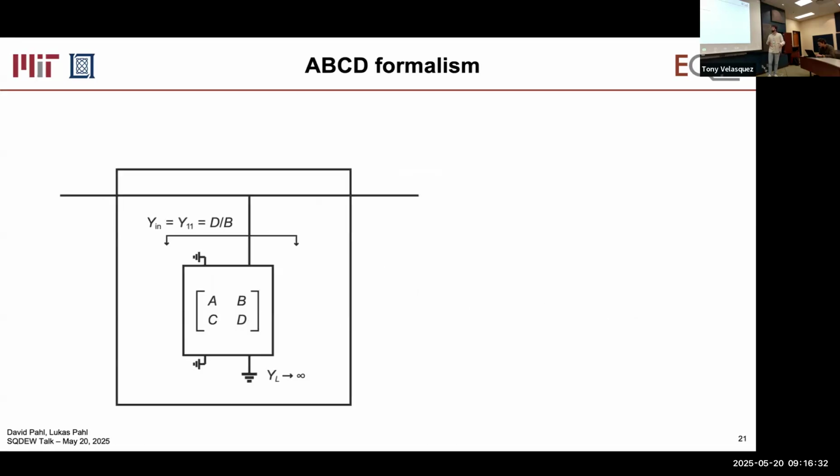There's one more ABCD matrix that I want to show that's really useful. Often in our circuits, we have something that's hanging off of a feed line, like maybe you have a feed line and then a resonator or something. You can take an arbitrary ABCD matrix, which can describe something more involved, like what we just saw.